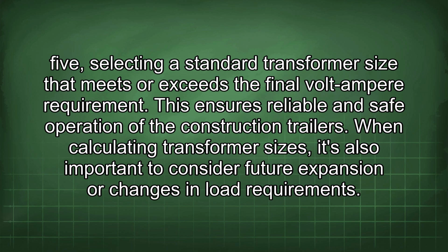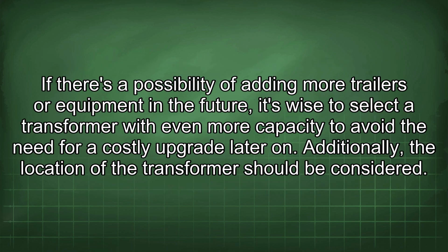When calculating transformer sizes, it's also important to consider future expansion or changes in load requirements. If there's a possibility of adding more trailers or equipment in the future, it's wise to select a transformer with even more capacity to avoid the need for a costly upgrade later on.